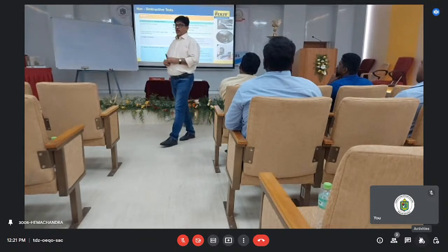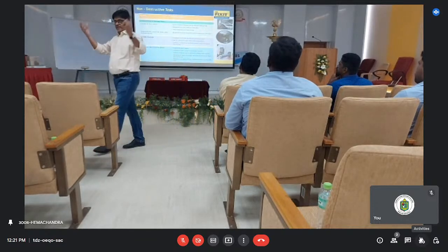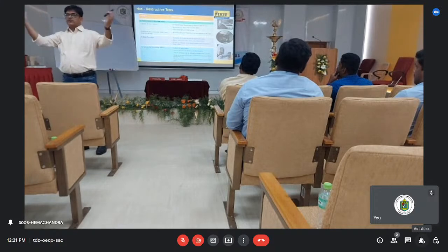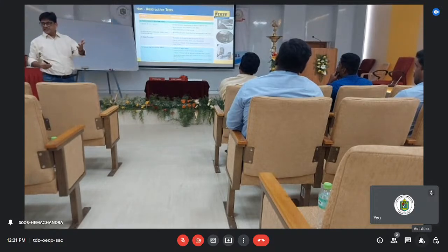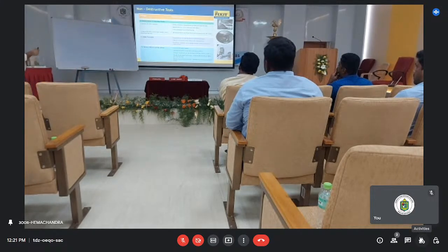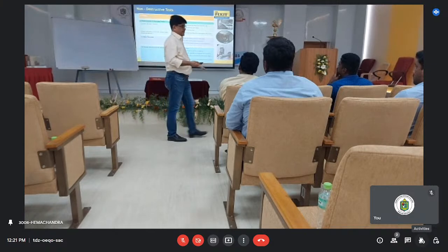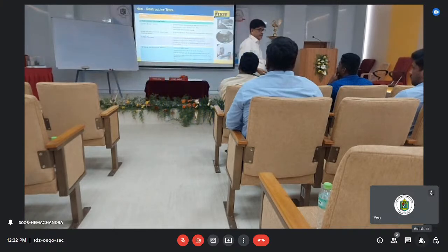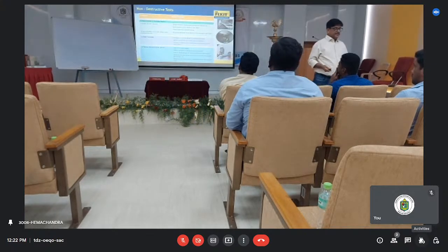Now, how you have to check it: you may not be able to go to the top, you have to go surface wise. That indirect method you have to use for the UPV. Then, for rebar corrosion, we have to check the structural member again. Rebar corrosion has to be checked. We have to do it with a half-cell potentiometer check, right?